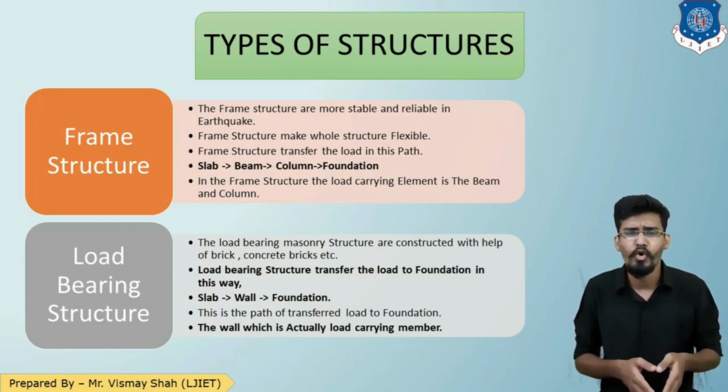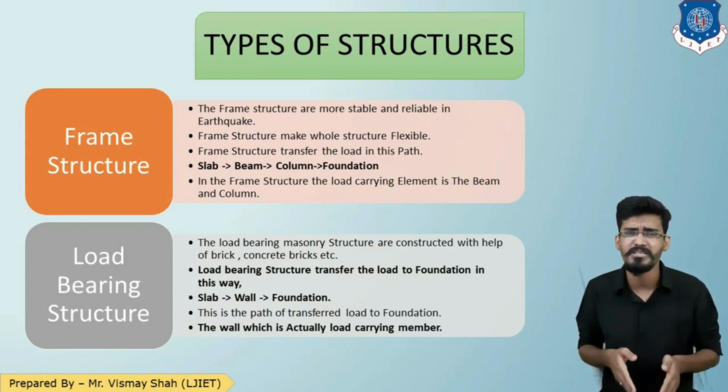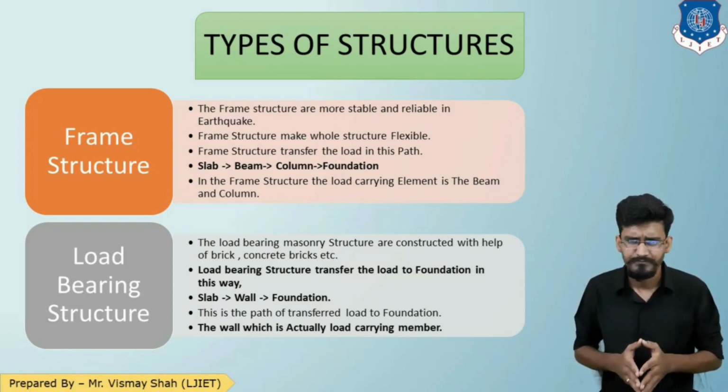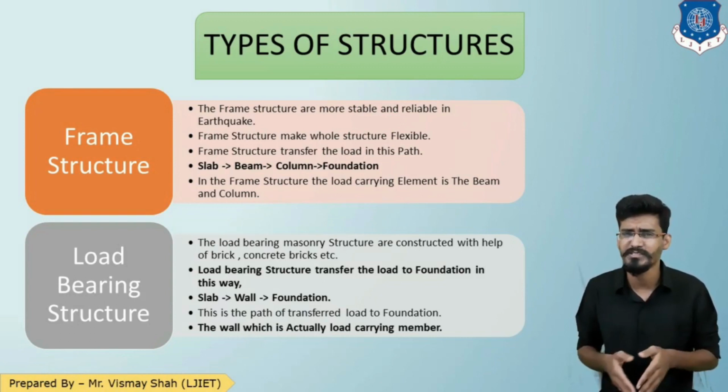Now, talking about the load bearing structure, the load bearing masonry is constructed with the help of brick, stone, or concrete bricks, etc. The load bearing structure transfers the load to the foundation in the following manner: slab to wall and wall to foundation. So in a load bearing structure, the load carrying component is the walls. So I hope we are clear about what is a load bearing structure and what is a frame structure.